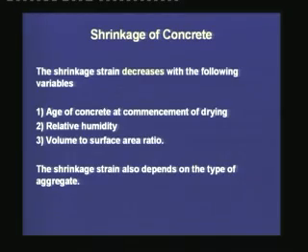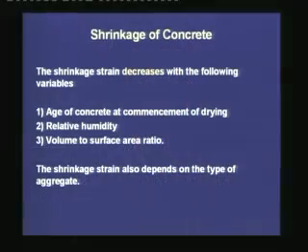Third, volume to surface area ratio. If the surface area ratio decreases, this volume to surface area ratio increases, and what we observe is that the loss of moisture is less, and hence the shrinkage is also less. The shrinkage also depends on the type of aggregates used for making the concrete.